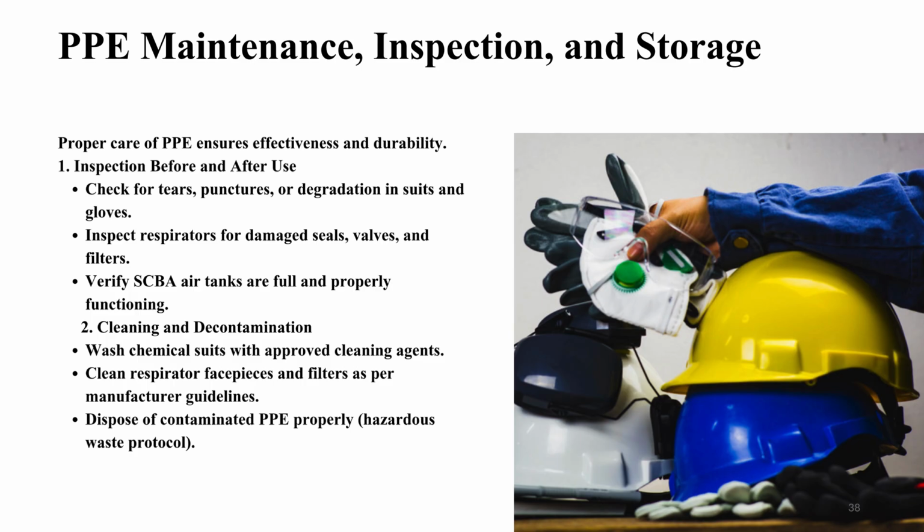2. Cleaning and decontamination. Wash chemical suits with approved cleaning agents. Clean respirator face pieces and filters as per manufacturer guidelines. Dispose of contaminated PPE properly, following hazardous waste protocol.